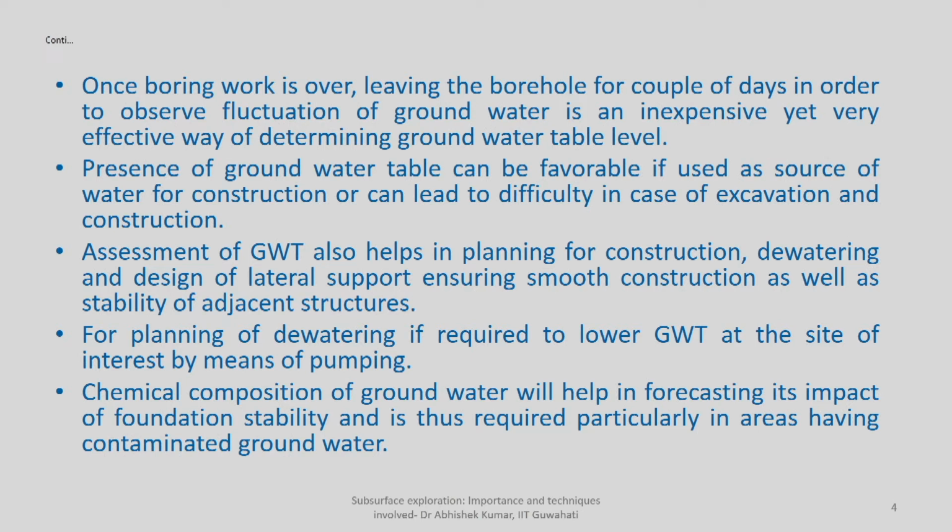So, what you do, you will leave the borehole for some time, so that the water table in it reaches an equilibrium position. You can observe it rather than going for a separate borehole, which is particularly used for determination of groundwater table level only, because anyway once you are exploring at the site of interest, you are going to drill a borehole.